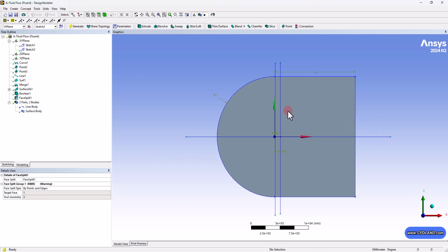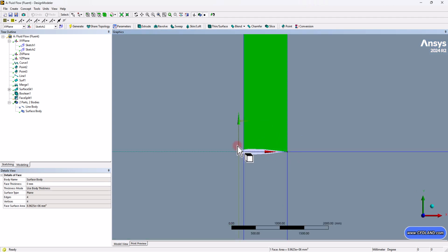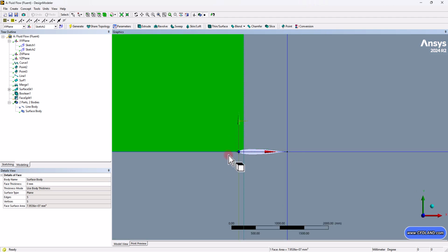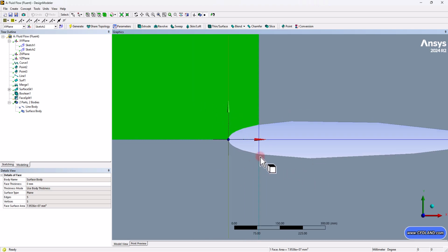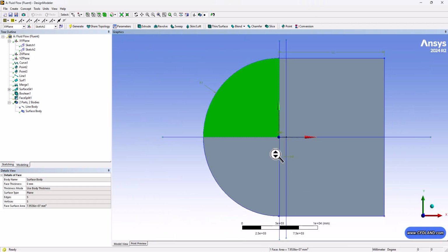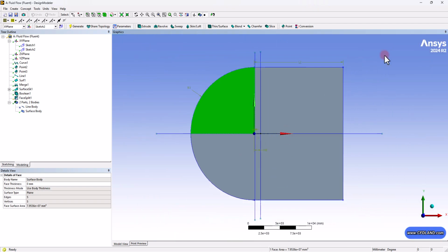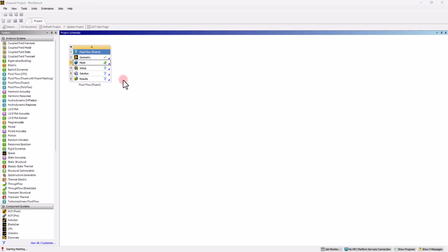So you may have not seen anything in here, but after selecting the face selection tool, you can see exactly what is going on. And this gives us the chance to define separate number of elements for every part of this domain. And in this way, we can establish a fully structured grid. So we are done with geometry, and hopefully we can continue into ANSYS meshing.